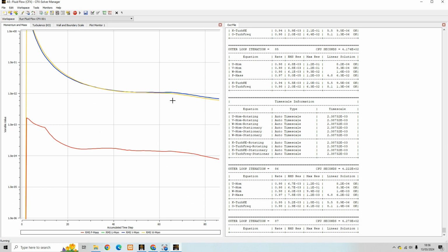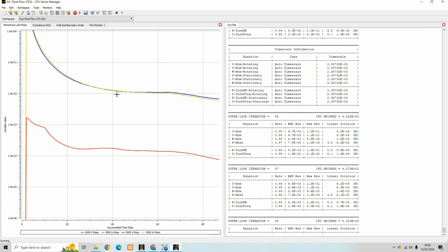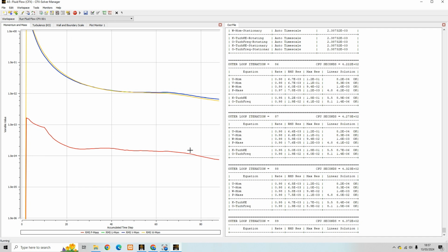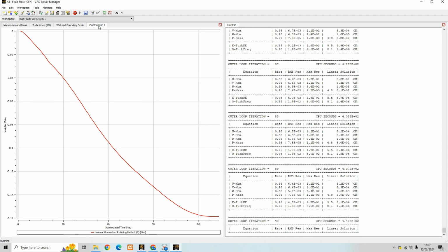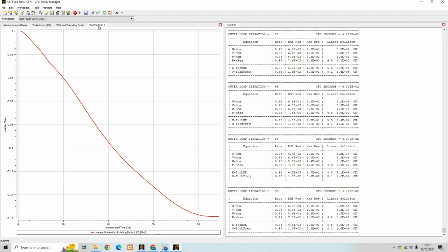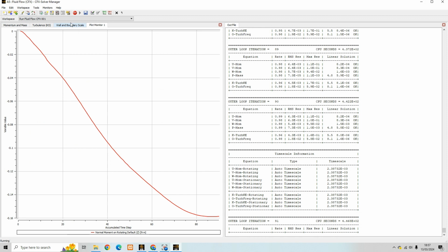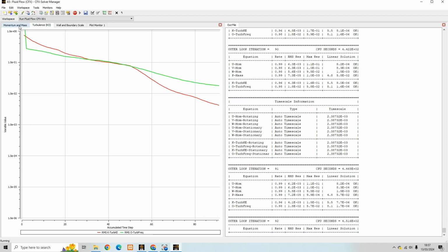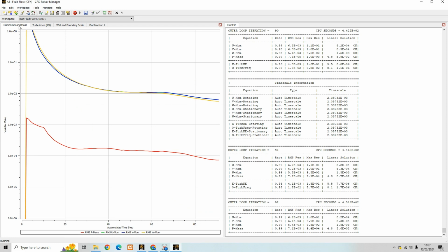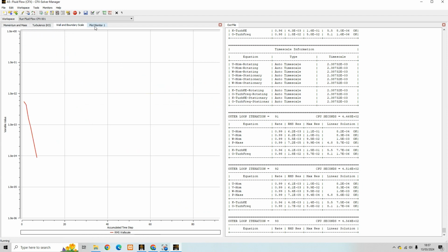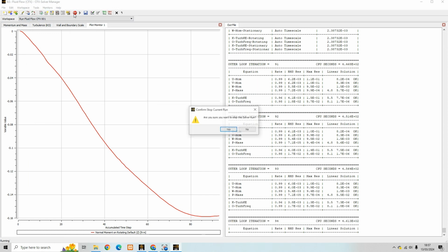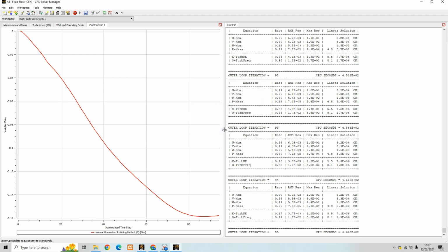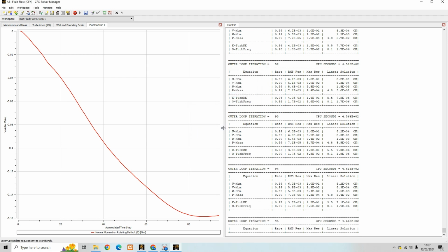And just seeing how that reflects in the residuals, we've gone through a plateau at about 10 to the minus 2, and then we seem to be decreasing further. Obviously, this is RANS and not a particularly well put together simulation, let's say. I've not taken much effort to make sure the cell qualities are fine, so I think we're doing all right there. Okay, so I'm going to stop that before it goes any further. I'm happy that we've got some kind of convergence, albeit relatively weak.